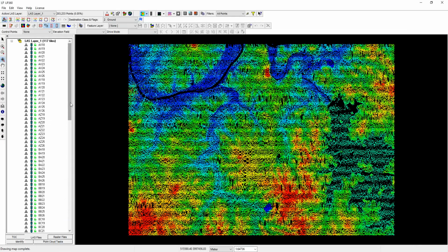You can see I've got a list of all of those LAS files that I read in, along with some icons. These icons are standard and relatively easy to understand once you know what they are. The first one, the little pyramid, is asking: is that pyramiding done? Is there a valid pyramid file for this LAS file? If there isn't, the little pyramid symbol will be red.